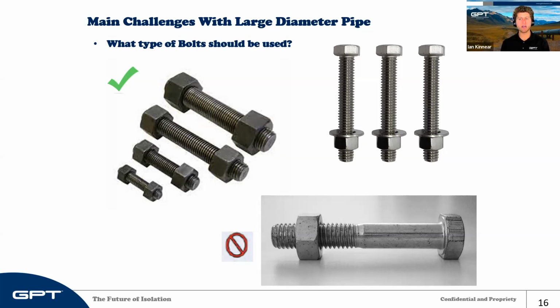Shoulder bolts are very common, especially in these larger bolt sizes. We see it quite often. And the issue is you can see here that these shoulders have a larger, uncontrolled diameter than the threaded section. So our sleeve can no longer pass over this. You're going to try to install and the sleeve isn't even going to be able to go over these shoulder bolts. So then you can't use the sleeves.